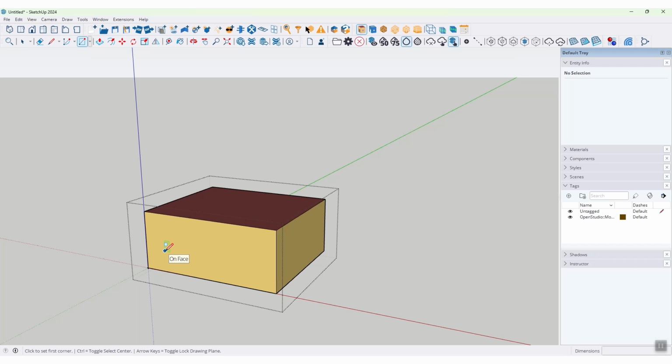If we are drawing the model in 3 dimensions, we need to make sure that the space is completely enclosed. This means that the floor, roof, and walls must be properly connected, and there should be no gaps or extra surfaces in the model. Now, let's draw a window on one of the exterior walls. To draw the window, we select the wall surface and create a smaller surface on it using the surface drawing tool. This surface should be recognized as a subsurface.